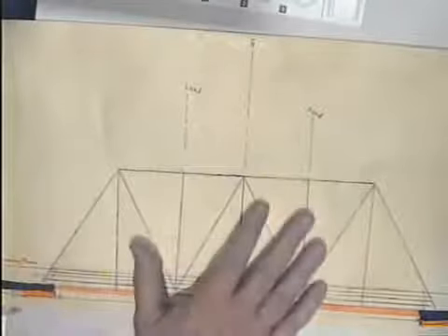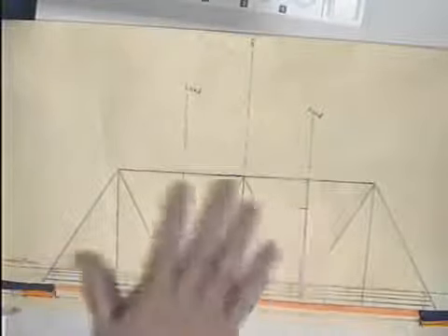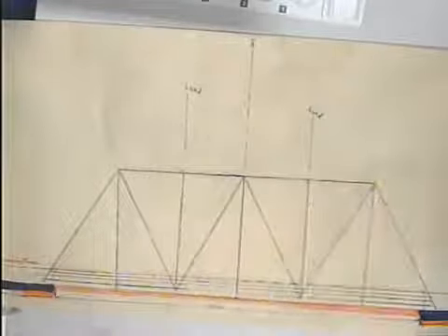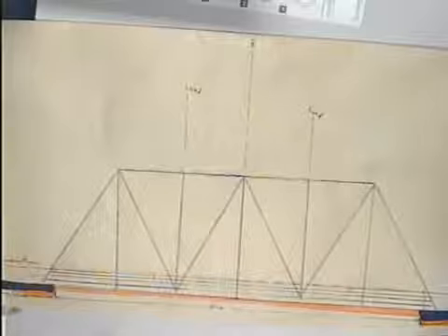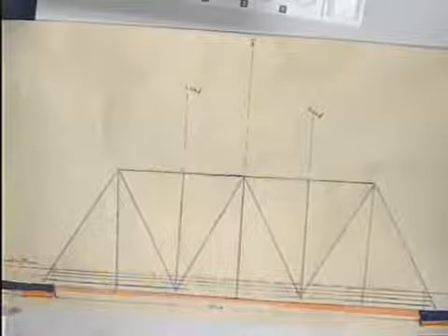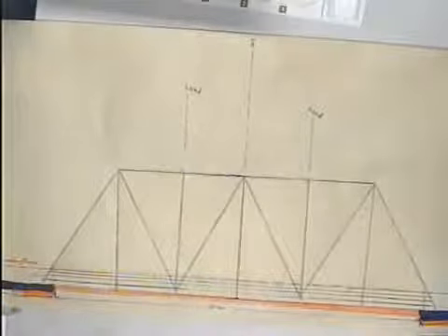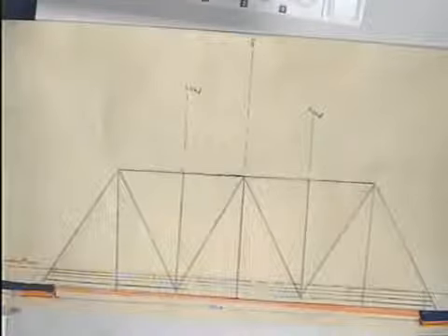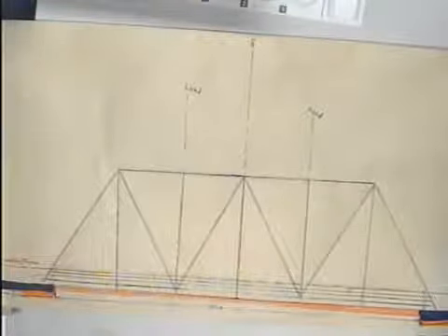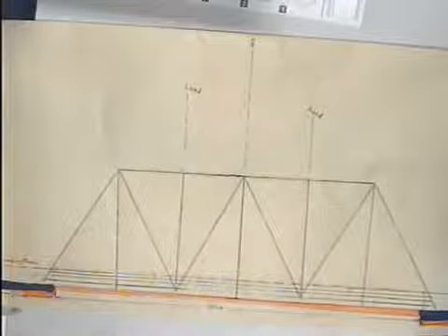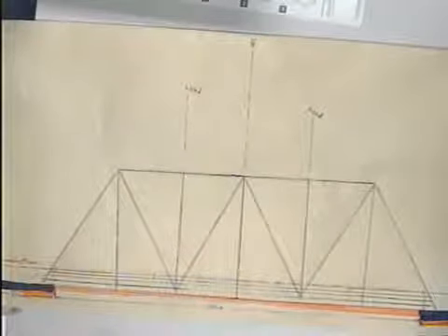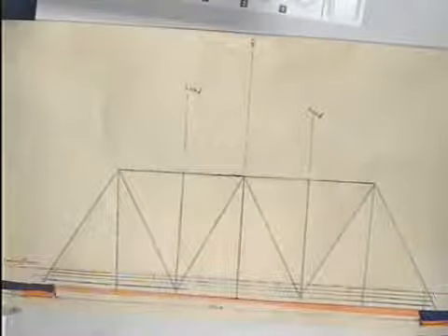Once you get the design done here and you've decided what to do, then you have to start working with the wood and the glue. What glue should you use? Turns out the best glue to use on wood is Elmer's Carpenter's cement for efficiency. Now, we're talking about efficiency here. We're not talking about total strength. We're talking about how strong it is for a particular weight. And the most efficient wood glue around is Elmer's Carpenter's glue, the sort of tan stuff that you get.